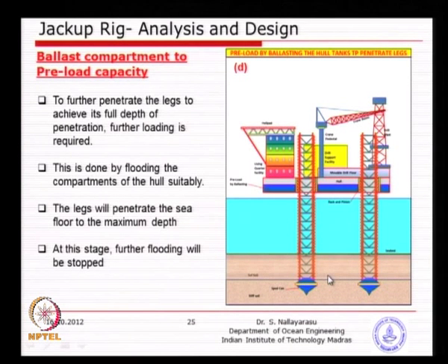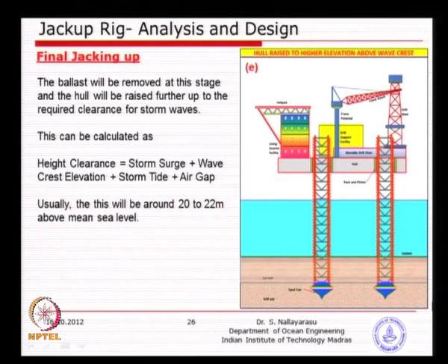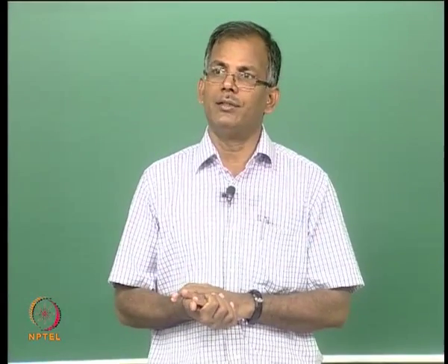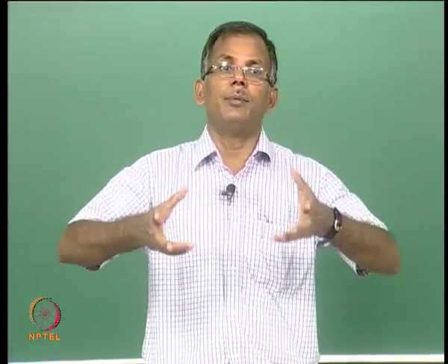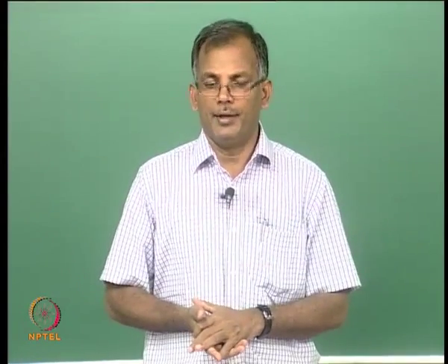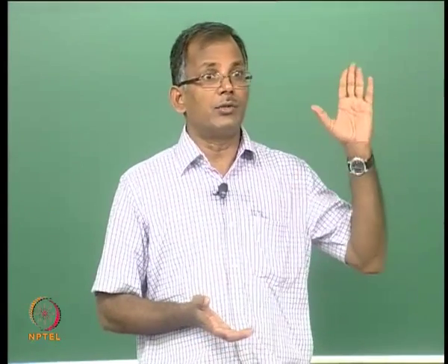So, you will need to pre-calculate and flood that much of water inside, and then ultimately you raise the hull to a level where the sea conditions during drilling do not affect it. Now, there is one thing you have to be careful about here: you do not raise this hull to a very high elevation, because stability could also be a problem, because you try to avoid a 100-year storm wave,